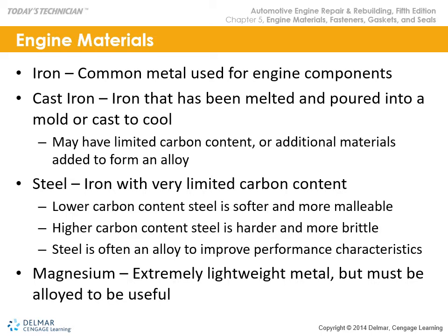Steel has a wide range of alloys that come with different hardnesses, and a softer metal is considered malleable. Showing here, higher carbon content is harder but more brittle. So when we get to tool steel, our typical mild steels will have what's called a Rockwell hardness in the 30s. We get to steel alloys, it's in the 40s, and we get Rockwells of 50, 60, and higher in tool steel, like our drill bits, our taps and dies, and other types of tooling.